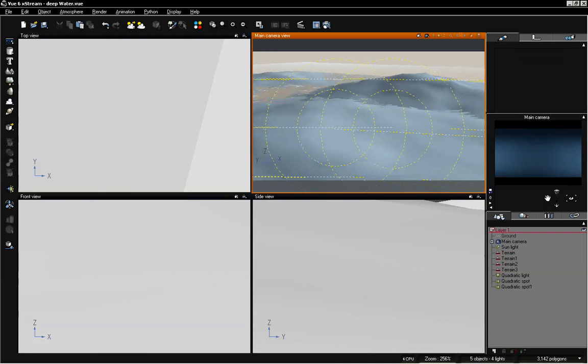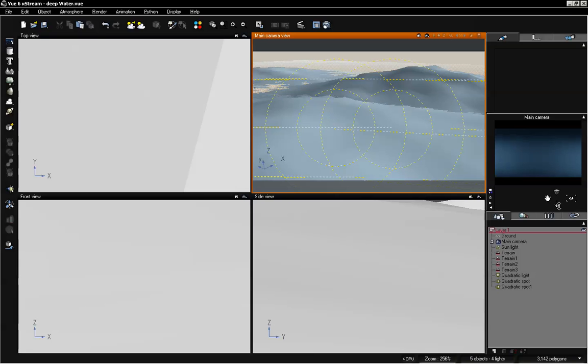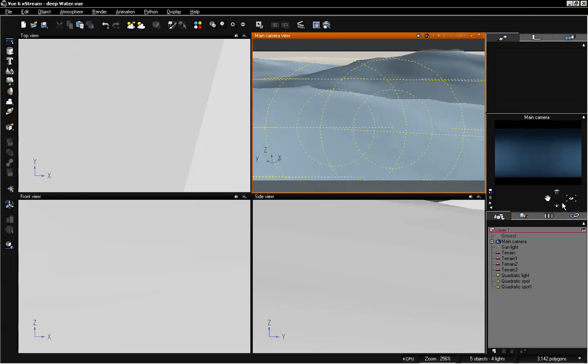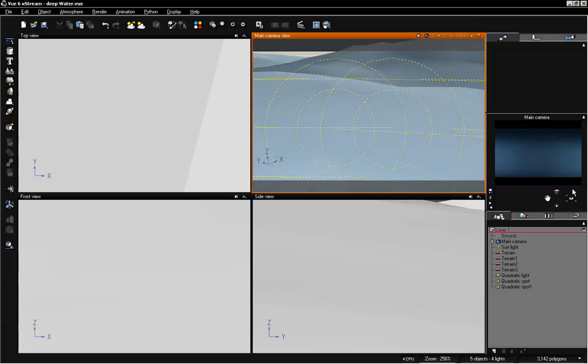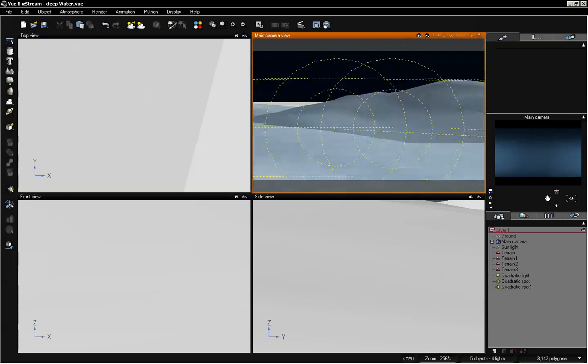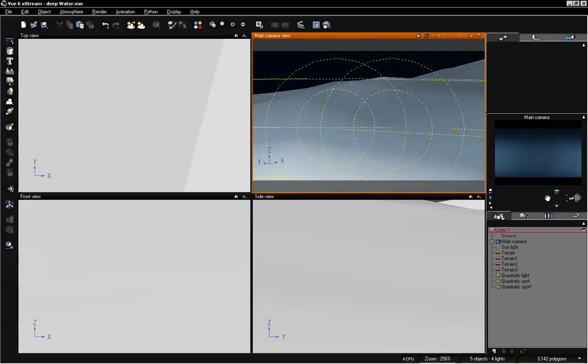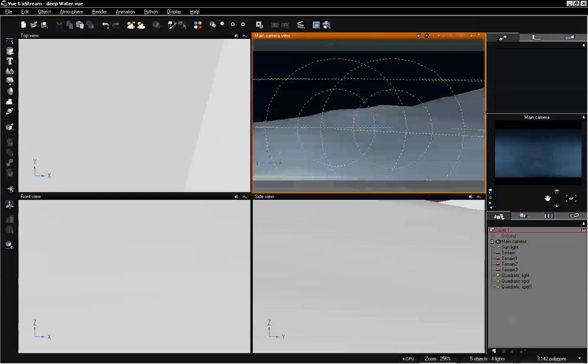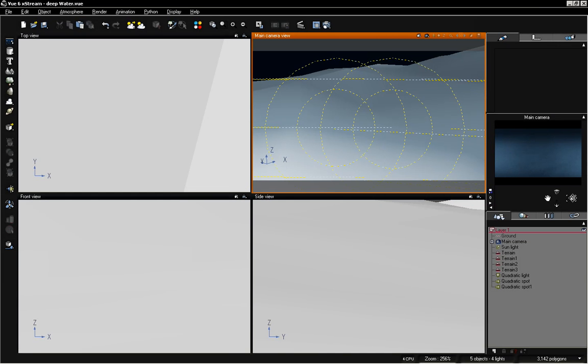And now we can just start to move in towards the scene and our terrains that we have. And we'll start to see those show up once we get close enough. Now we're really not seeing a whole lot because we've increased the overall size. So what we need to do is also increase the power of our lights, because now we have something a little more real scale, and we can see that little peak right there, but that's going to disappear very quickly as we move away from that object.